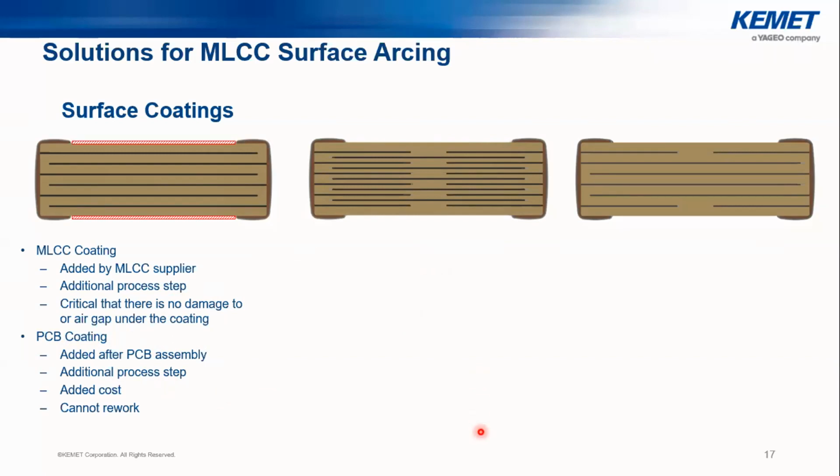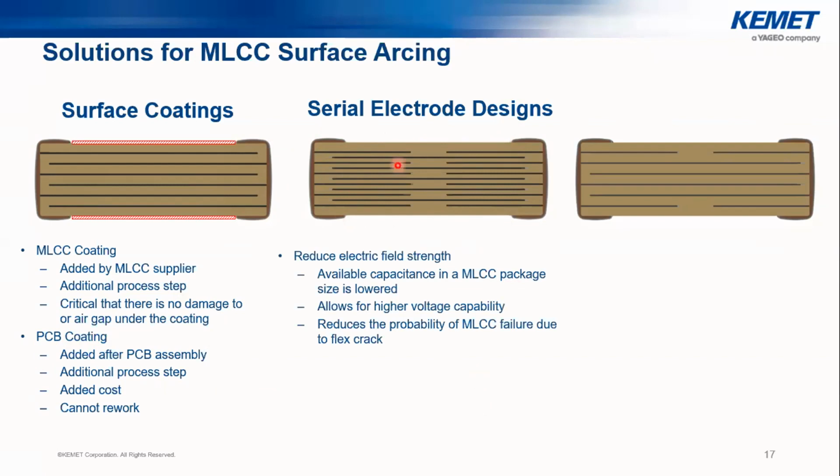The other way is through the serial electrode design. As you can see here, when we have two series parts inside the MLCC design, we reduce the electric field strength this way. But in this way, we have two series capacitances, so we reduce the capacitance capability inside the same size of MLCC.